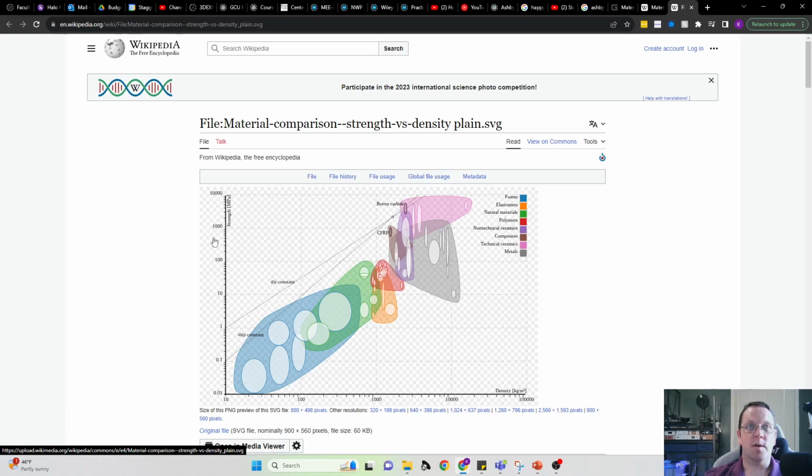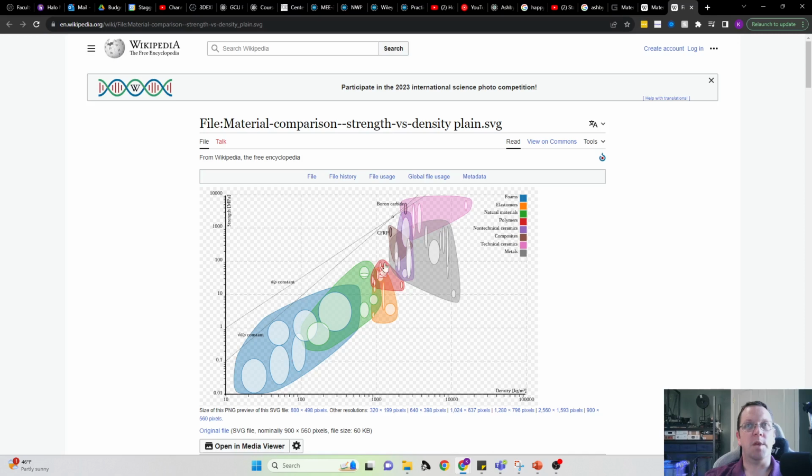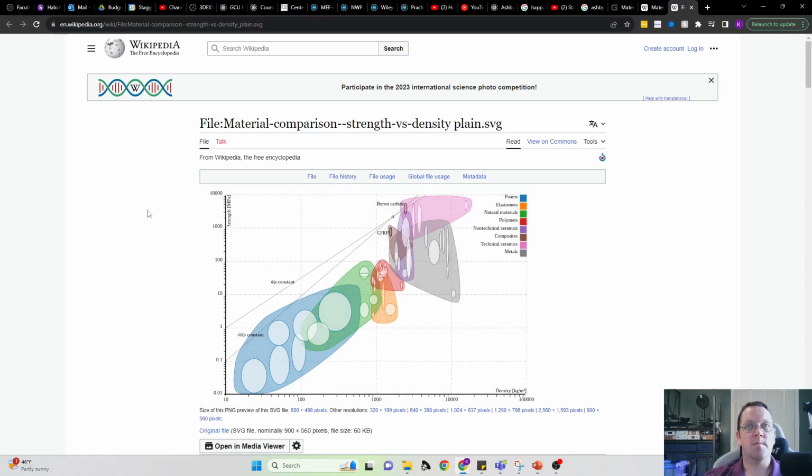The ratio of sigma to density is the one that he was using in that design, and it's fairly traditional because it gives you a straight line fit over the course of these materials and allows you to easily select based on where it is. So you'll have to manually draw on one of these Ashby plots in order to find one that fits what your definition is. But in terms of being able to select the right material for a given application, we'll take a look at the